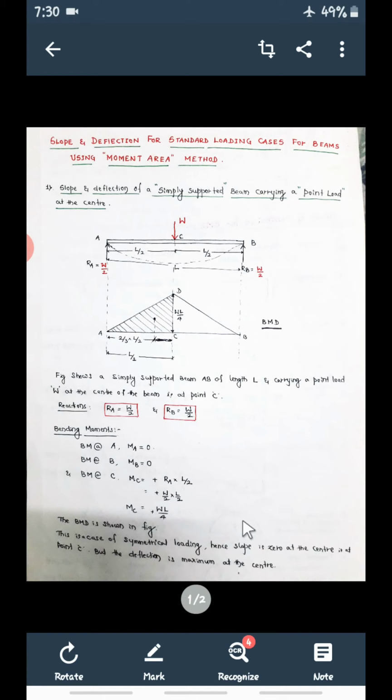Okay. So next, now try to understand here. One more dotted line I have drawn here. This dotted line indicates the bending shape of the beam. Now when the load comes on this beam at point C, the deflection here will be 0 because of support. The beam is not going to deflect here. The beam here also, because of support, is not going to deflect.